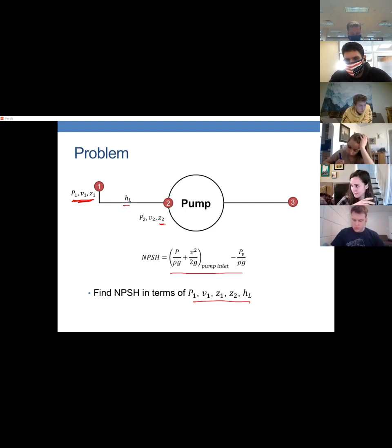So what we're saying is if it comes out of the pump, the pressure starts to drop again, and so maybe cavitation would happen again. You know what, I can't imagine cavitation happening after the pump if it doesn't happen before. I don't think you get a situation where that happens because you always have that low pressure going into the pump.